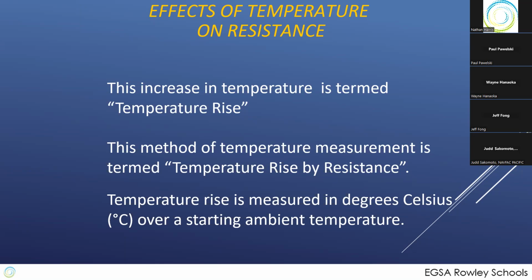Again, this is especially critical in some place like Dubai, because not only do you have the rise in temperature from the load you're putting on, but it's rise over the ambient. So the temperature coming in makes a big difference. And so you must understand what the temperature ranges are for your genset and what the ambient temperatures are that you're working in, to tell whether all of the load the commander is insisting that you put on this genset can actually be run continuously without the machine failing on them.